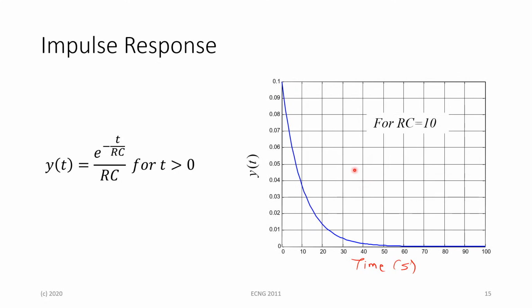Right, so we see that when we evaluated the impulse response for our RC circuit, the fall time here was about 60 seconds. We still had our initial transient response that we observed in the previous step response graph, as well as a steady state value for when we move towards our final value with respect to our system, when the capacitor in this case is fully discharged.